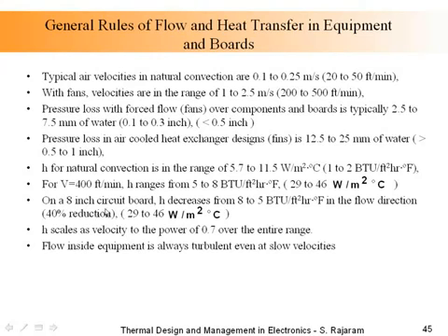So what you will find in most electronics is that the heat transfer coefficient scales as velocity to the power of 0.7. And this is also something that most of you who are familiar with heat transfer can relate to, because you remember the heat transfer equation, Nusselt is equal to 0.023 Reynolds to the power of 0.7 Prandtl to the power of 1/3. It's exactly what happens in electronics.